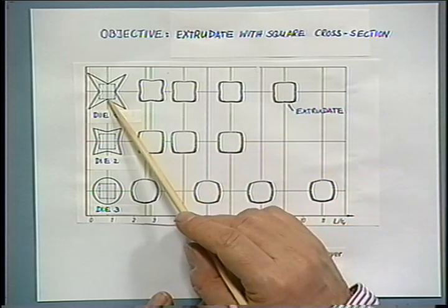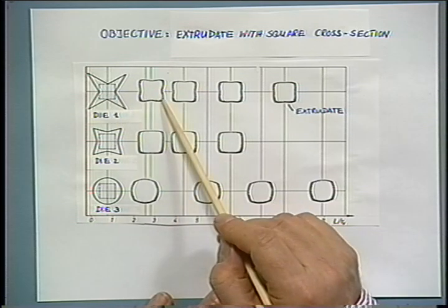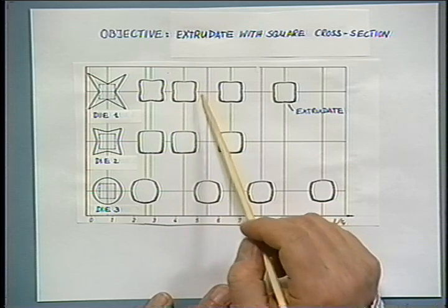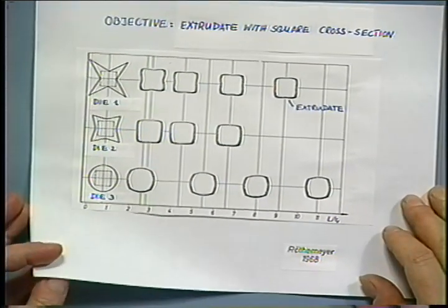But here he overdid it. He put in very sharp corners, and you can see there's an overcompensation. So just making those profiles is very, very tricky, and it's due to the shrinking and the swelling of the material when it leaves the die. Complicated geometry, hard to predict.